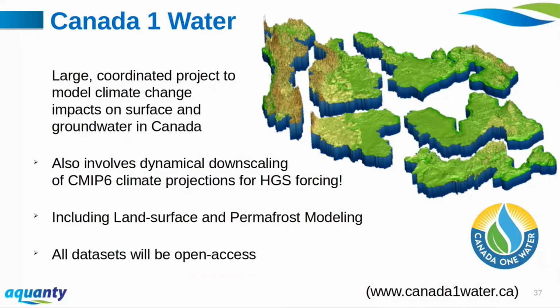The data sets themselves will be at higher resolution than we will run the large basin scale models, and most of them will be high enough resolution that they will be suitable to just carve out a little area of that and run a higher resolution model, something like the Grand River model or even higher resolution. So a lot of the input data sets will actually be something like 300-meter resolution, right? Like the DEMs, even higher resolution. So this will really facilitate carving out small models and zooming in, but also building larger models and having them based on a consistent database, right? So that you can really make a modeling chain where you can solve this boundary condition problem with that, right?